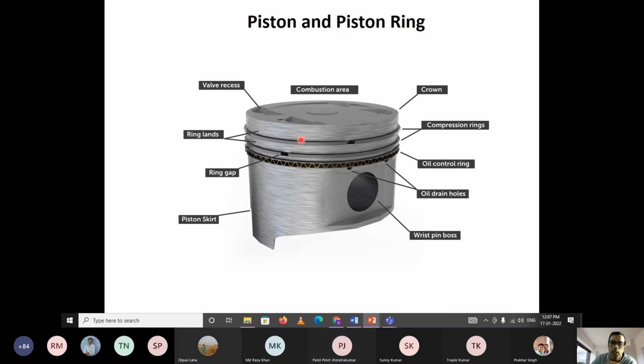So you may assume that if it is an 80 mm bore diameter, then the diameter of the piston is around 79.5 mm. There is a gap, and even a small gap is enough to cause a lot of leakage if the pressure is more than 2-3 bar.